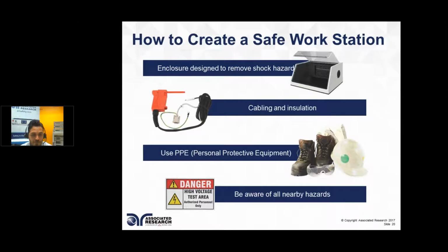Our 5 kV instruments, again, the insulation on those leads goes up to 30 kV. So it's important. You've just invested a lot of money into this high-pot tester to verify that your products are safe, and to sell these products and turn a profit. Well, it's important to also recognize your accessories and your leads. Those are a huge part of your testing system.